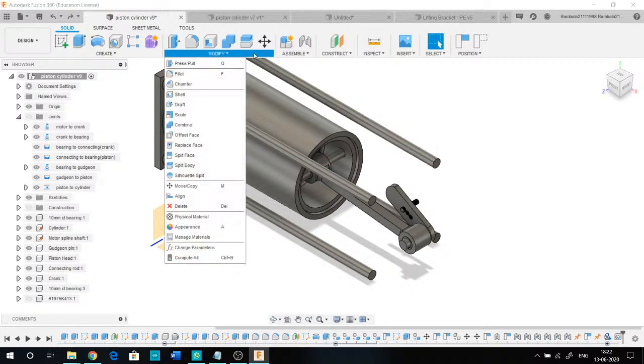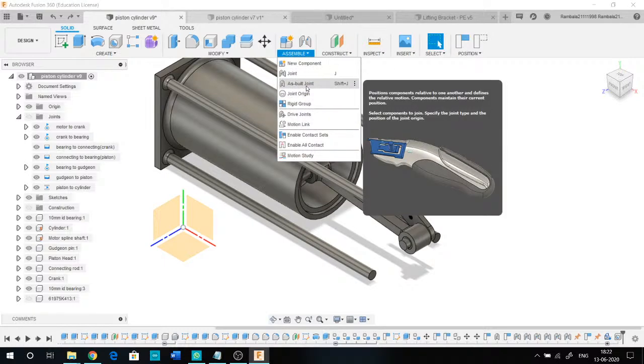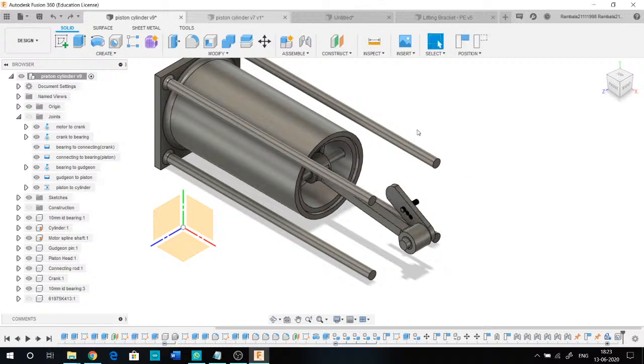For the assemble joint, you first need to align the components. You can align them in whatever position you need, and then create an assemble joint for those two components. Once they are aligned, you just select the pair of components and the type of joint. This is much simpler, but in my opinion these two approaches have their own pros and cons. Try using trial and error; only you can identify which is best for a particular joint. I hope it's clear, Amal.